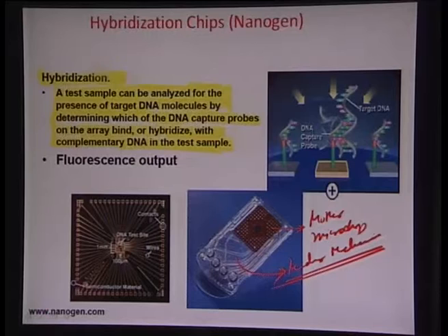If you look at the back side for the electrical connectivities of this particular chip, you can find out very easily how it looks. Essentially these are all the different contacts that you provide in order to supply the electrical voltage to the different array of pillars or posts, principally gold, which are carved or manufactured on top of the chip. This is the reverse circuitry of this chip, which gives you the connections to the various electrodes on the surface, and you can keep biasing them positive or negative depending on your requirement.